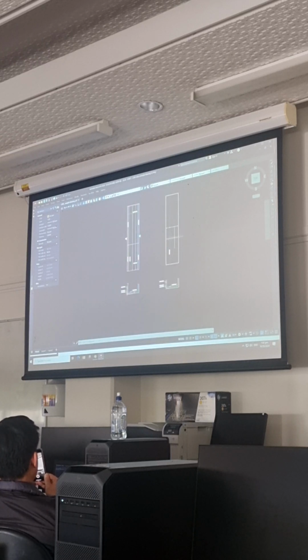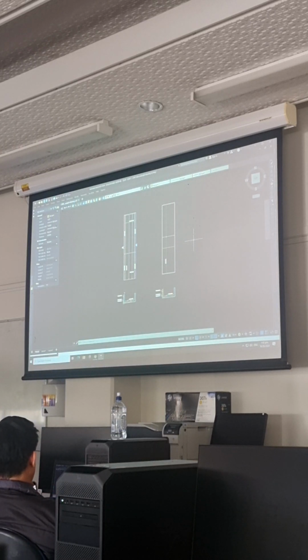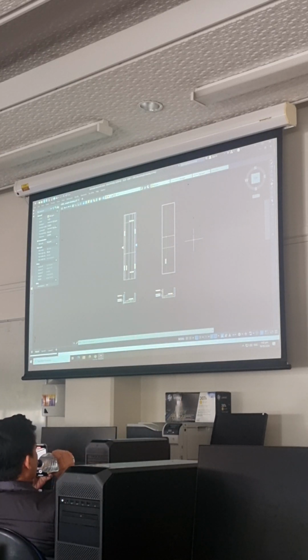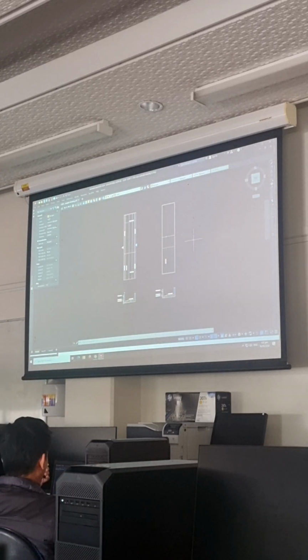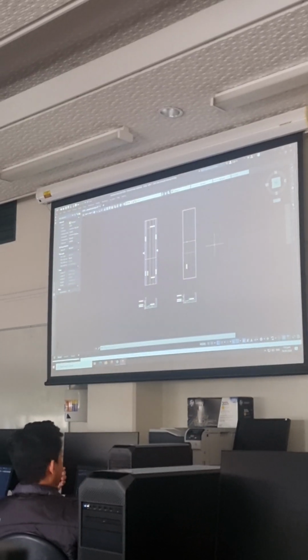Where are you likely to get a job doing this? For a steel company that do reinforcing. All around Auckland there's 2 of them, because you're doing it ready for the steelie to lay it. In a consultancy, they tend to just show 1 bar, how far it goes, what sort of diameter it is, and the spacing. They don't worry about how many there are. You don't normally have to calculate that in a consultancy, but if you're working for a design and build company, yes, you would have to work out the exact amount and do a bar sheet.